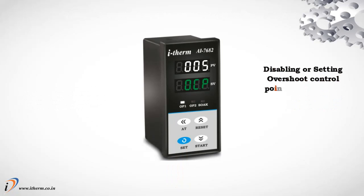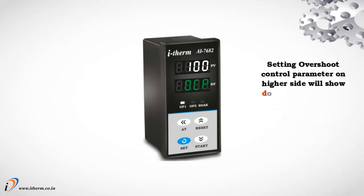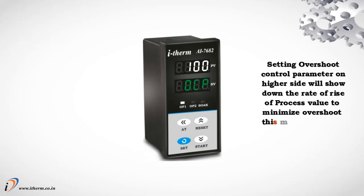Disabling or setting the overshoot control point parameter on the lower side will increase the rate of rise of process value, which may cause overshoot. Setting the overshoot control parameter on the higher side will slow down the rate of rise of process value to minimize overshoot. This may cause delay in reaching set point.